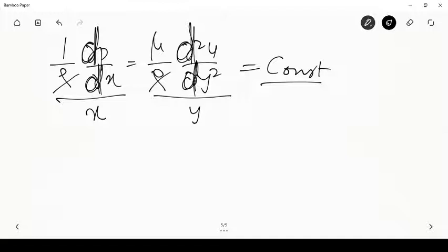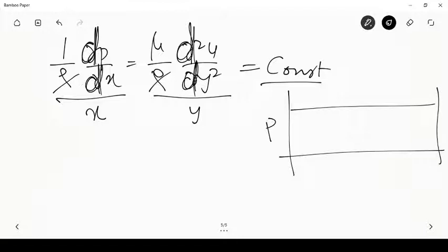So suppose I say the duct is here, there is an inlet pressure P and let us say an outlet pressure of 0 relative to, let us say, the atmospheric pressure. The outlet is at atmospheric pressure and the inlet is, let us say, at a pressure P1. Then the pressure variation in the fully developed region will be a straight line. The pressure will go from P1 to 0 in a straight line in the whole thing.